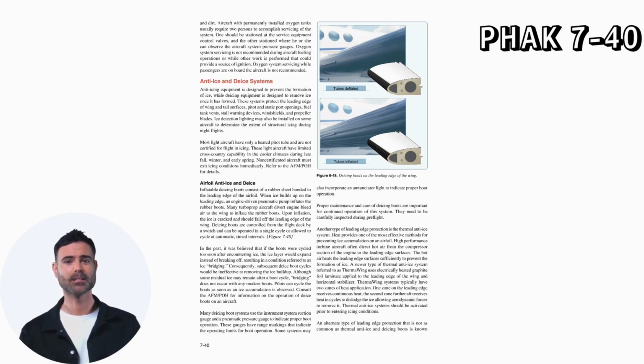Anti-ice and de-ice systems. Anti-icing equipment is designed to prevent the formation of ice, while de-icing equipment is designed to remove ice once it has formed. These systems protect the leading edge of wing and tail surfaces, pitot and static port openings, fuel tank vents, stall warning devices, windshields, and propeller blades. Ice detection lighting may also be installed on some aircraft to determine the extent of structural icing during night flights.